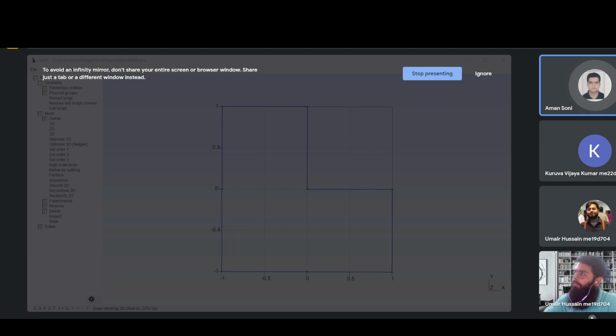So this is the 2D platform you are selecting to draw something. Yes, right now I'm drawing only a 2D mesh, but we can do 3D as well. So you are using the sketching tool. Yes, we can add basic 2D geometries. I started with points, then joined them with lines. There are others also: the circle, the ellipse, and all that. I forgot to define a plane surface. After making the 2D geometry, we have to define a 2D plane.